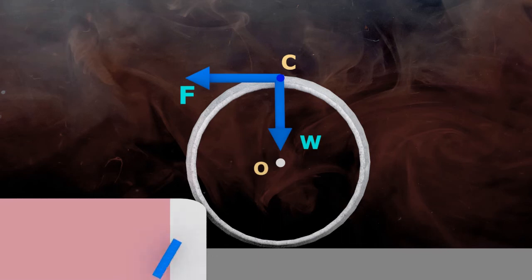The third force is the reaction from the curb R acting at point A. Here, as the other forces, that is force F and weight W, are intersecting at point C, the line of action of R must pass through the same point C to maintain the state of equilibrium, as we discussed in the previous problem. Otherwise, the system of forces will produce torque and start rotating the pipe. So, R must act along the line joining points A and C.